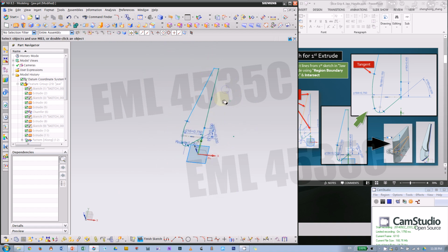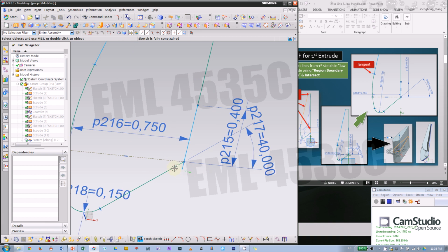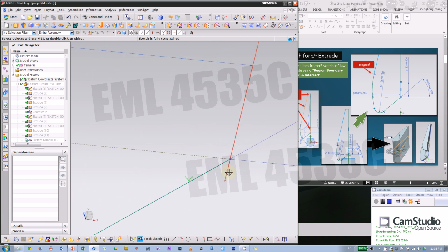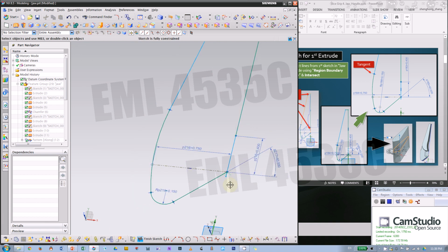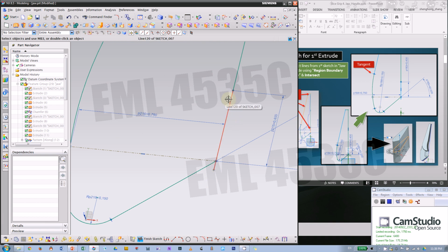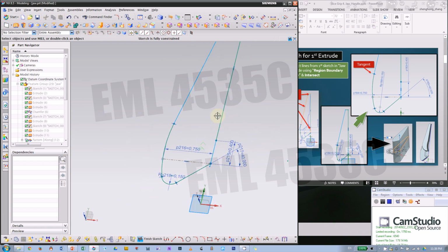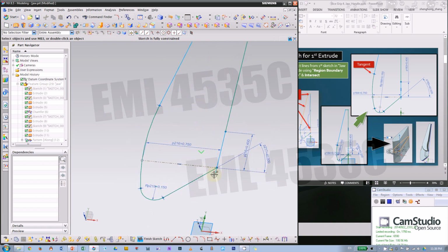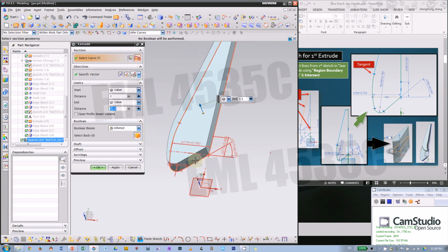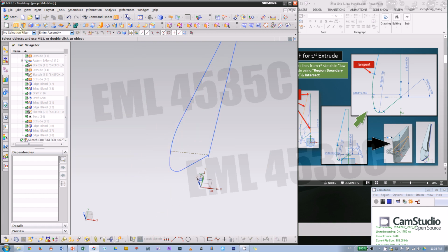All right, next step, we need to extrude this. Since those curves are not in a closed loop, you see this is sticking out here. You can trim this off, but once you trim this off, this line will lose association to your first sketch. That means you probably get an under constrained sketch. So I would just leave this alone and try to extrude this from within this sketch, or you can finish the sketch and extrude.